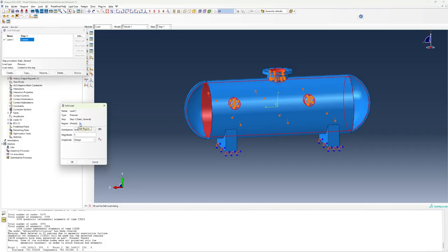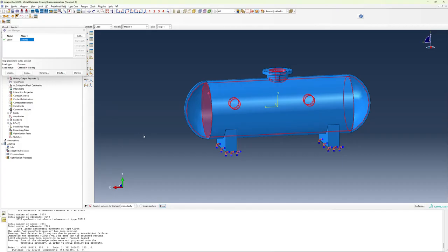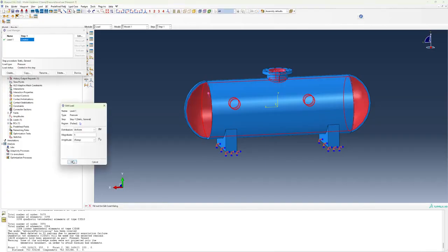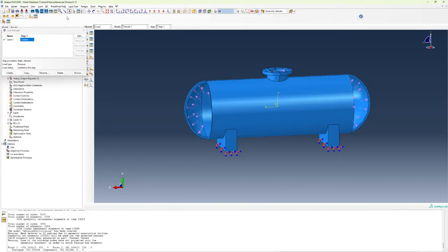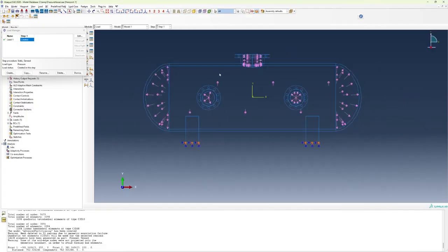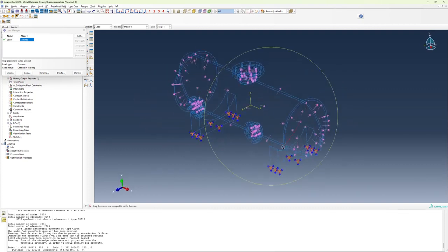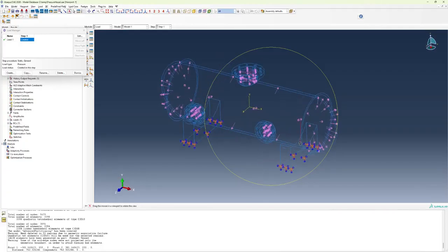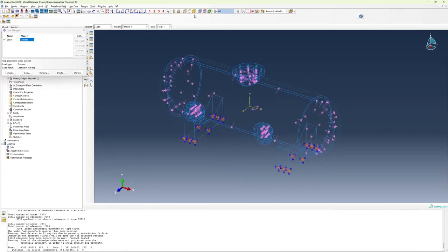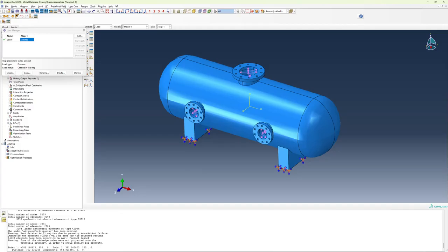Please click on this icon where it says Edit Region. Now hold Shift, click on this surface, click on this surface, and hit done. Okay, now let's show everything once again and double check whether everything is selected. You can see that all the internal surfaces of the geometry are selected. Now let's go back. So now we have pretty much defined everything that we need for the simulation.